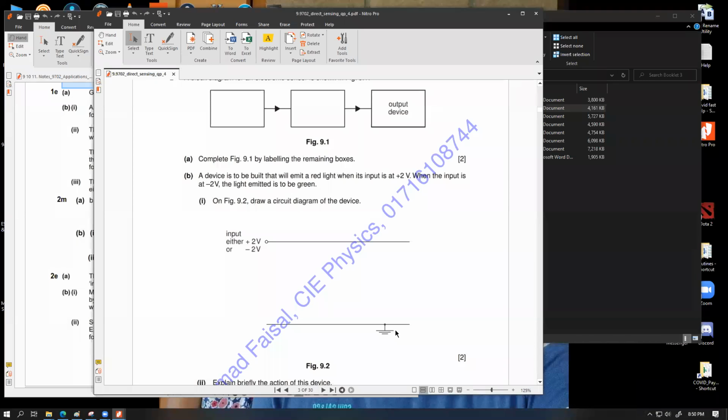Which is possible to achieve for metal bodies. For example, if you have aluminum body, or if you have basic iron made chassis. But for cases where you have carbon fiber made bodies, then you have to have artificial earthing circuit, or you need to have your entire electrical circuit working exclusively through your battery. You are not going to have a basic earthing. But earthing essentially mean that we have such a huge reservoir of electrons that a small bit of addition or subtraction would not change its voltage effectively.